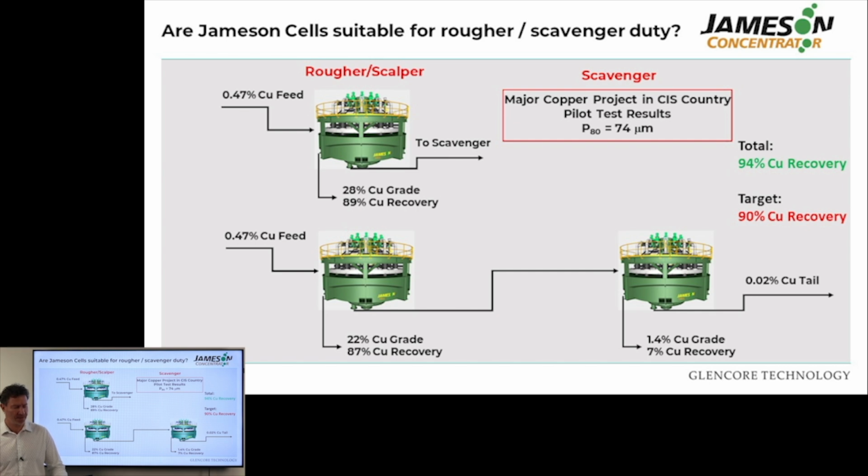application. First we ran the feed through just one stage of rougher scalper duty, and then we ran the same feed through a rougher scalper and a scavenger duty.